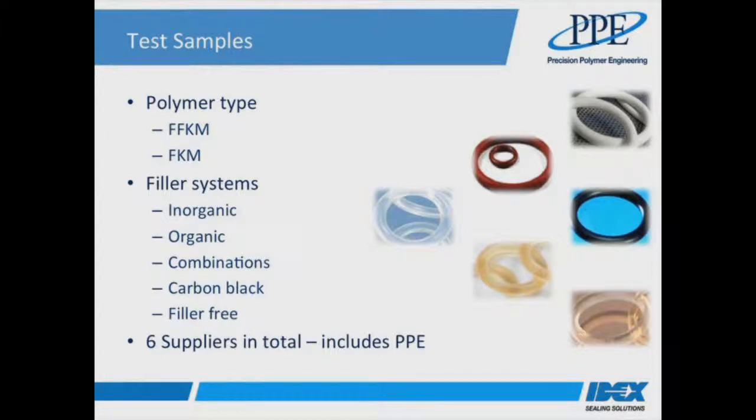We limited the number of base polymer options around those that we believe are most likely to be used in the more critical applications. Hence, we also had more FFKM materials on test than FKM materials. In total, though, we had about 30 different samples or materials, although not all in equal quantities. The characterization process is also still somewhat work in progress, so right now there are still a number of samples to be tested. I should probably also mention that during this phase, the samples were simply all directly exposed to the environment with no additional stress or stretch applied to them.